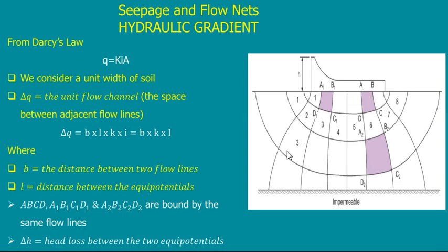So I measure these numbers 1, 2, 3, 4, 5, 6, 7, 8. And then I measure these channels. This is important to concentrate because, as I said before, I already have 3 channels. This is 1, 2, 3. But here, it is not a full channel. This is part of its channel. So when I come to measure the number of flow channels, I can use a percentage or a fraction.